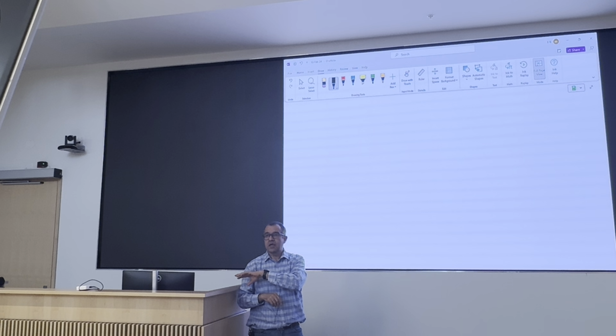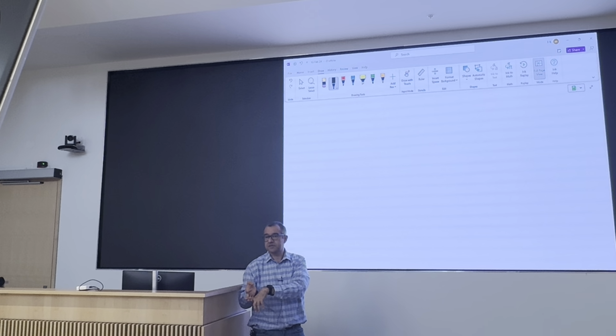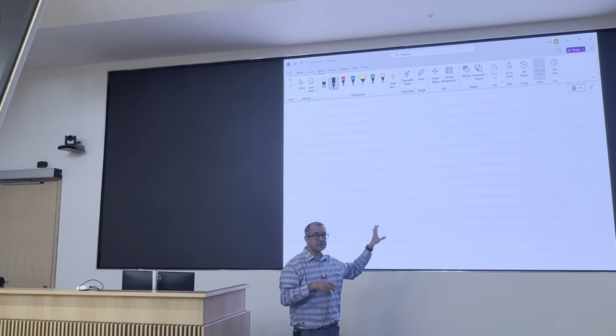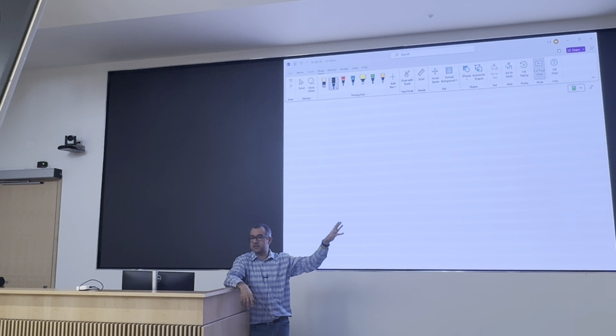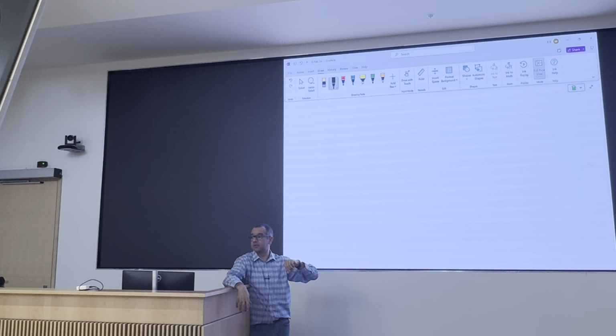When you look at an integrated circuit, you see a lot of transistors and very, very few resistors, because resistors are expensive. In IC design, area determines your cost, area of the chip. Resistors are big; for one resistor you can have 50 transistors. So if I can use 20 transistors to do my job, I'll use 20 transistors instead of one resistor.